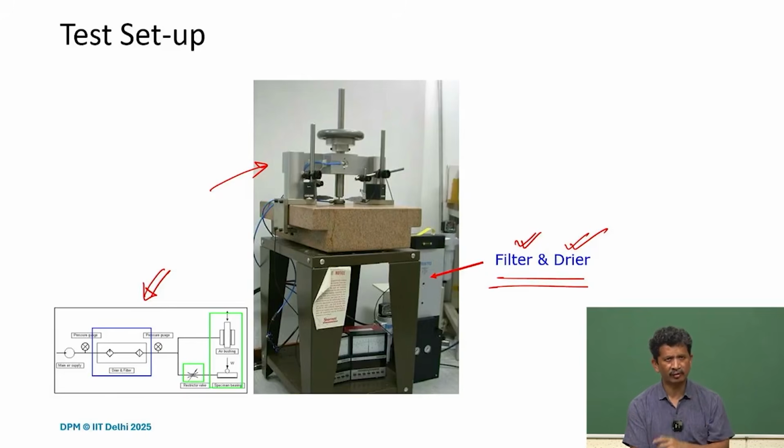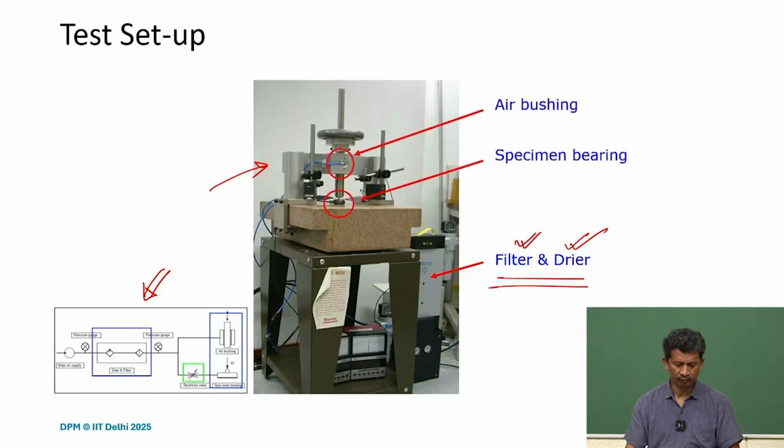The air gaps are of the order of maybe 4 to 10 microns, so a particle can always scratch the surface. So we work with this. So, the air bushing, and you can see this blue line. It's for the air supply, and the spherical bearing is there.